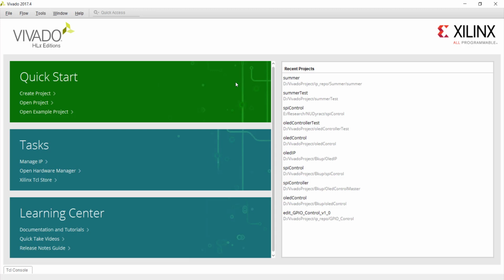You start a project and go to tools and say you want to create a new IP and choose the IP. And when you choose the IP interface, you choose AXI4-Stream instead of AXI Lite, the way we did last week. Last time we chose AXI4 Lite. Instead of that, you just choose AXI4-Stream. That is one way of doing it.